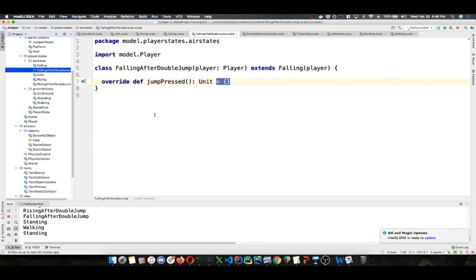So every time you hit a button that's going to change the functionality of any of the buttons, you just hit a state transition, you're in a new state, and now you want to ask yourself, okay, I have this new state, what's all the behavior in this new state? And in that state, you're going to have some buttons, all the buttons will have some specific functionality, and some of the buttons are going to change the functionality of at least one other button. Well, you just hit another state transition there. So each button that you can press that changes functionality, you hit a state transition. What's the functionality in that new state?